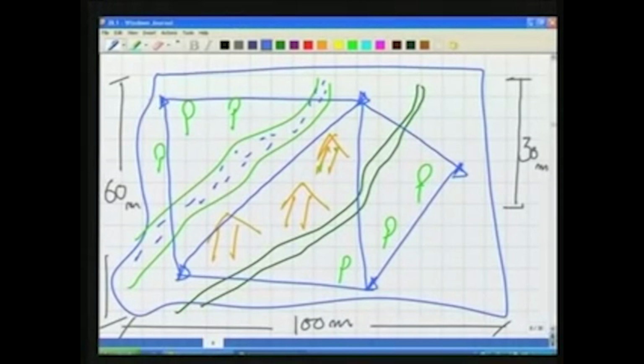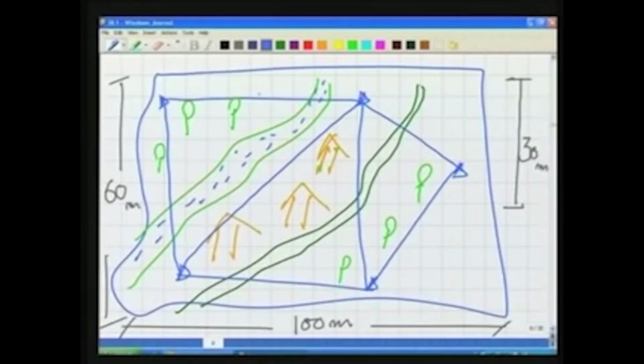Now, what is the meaning of that? Once you have gone into the ground, you can do these measurements easily, isn't it? You have got the tape, you spread the tape and measure these distances. The only thing is keep your tape horizontal, because we consider our earth, over a small area, to be flat. So, by keeping the tape horizontal between these 2 points, I can measure all these distances L1, L2, L3 and similarly. So, all these measurements are known to you.